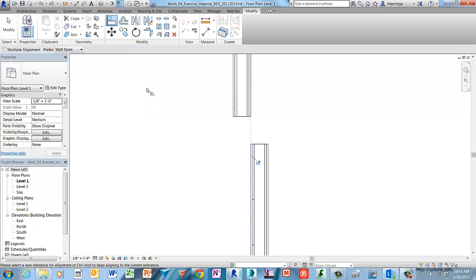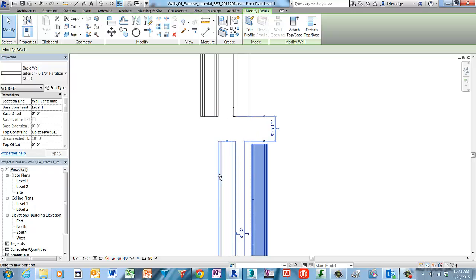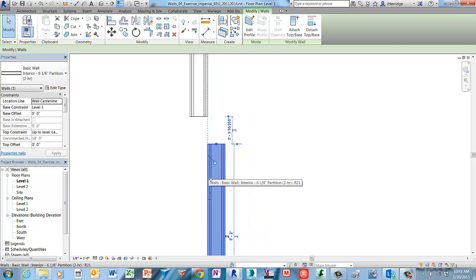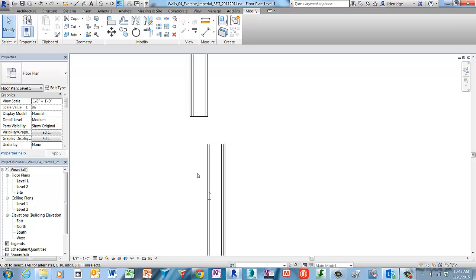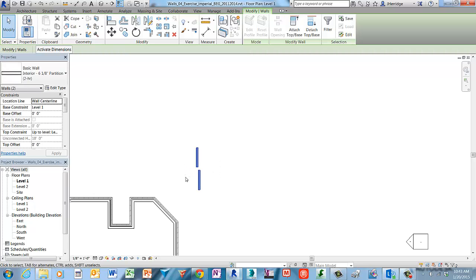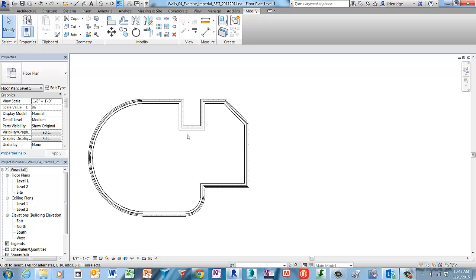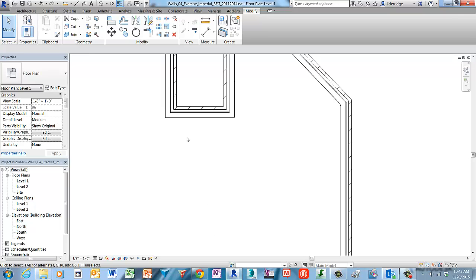In this case, I want to demonstrate that there is an opportunity to create offsets that still leverage the alignment constraints. So in this case, I made the left edge of the right wall the reference plane, and then I chose the right face of the left wall to align with that plane. And again, the alignment constraint is enforced. This concludes this instructor demo. Let me clean up the environment and let's move on to the exercise at hand.